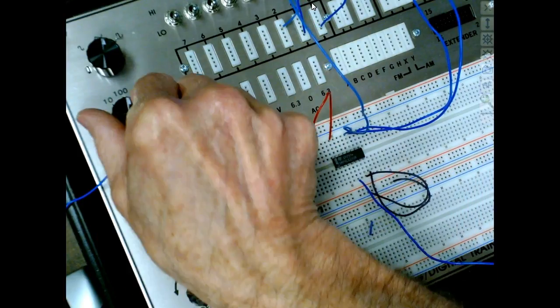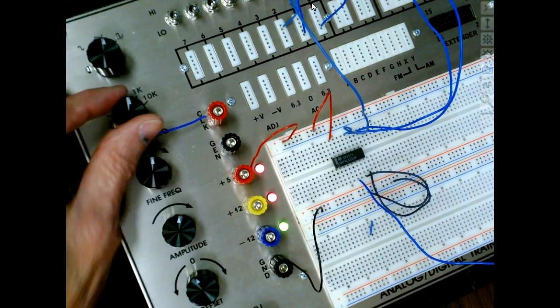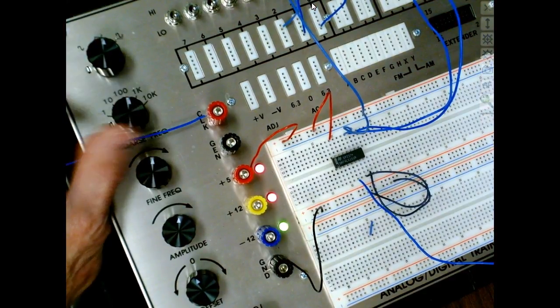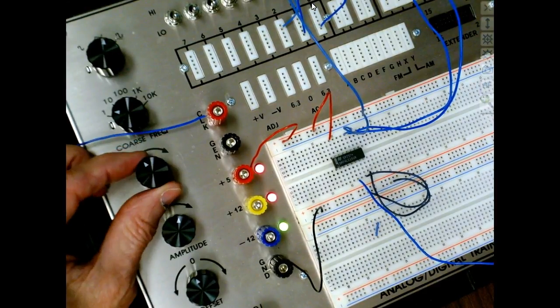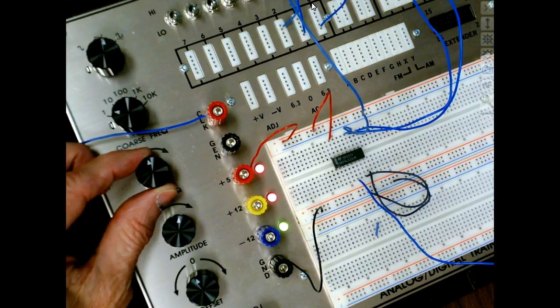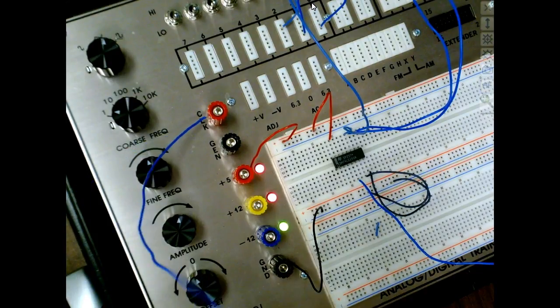And then this is where we set our frequency right here. Now this is not perfect. You can check it with a scope. So this is your rough, this is your coarse. So if I put it on 1 hertz, that should be fine. And then this is where you'd fine adjust it right here. That makes sense? And most of the time these frequencies are not critical. All you're doing is looking at, if you put a clock in, you might be expecting a clock out or whatever. So this is a lot easier to use than trying to use that function generator. Now the triangle wave, we had to use the function generator, right? You understand that? So I'm going to take this and hook it up to one of our inputs.